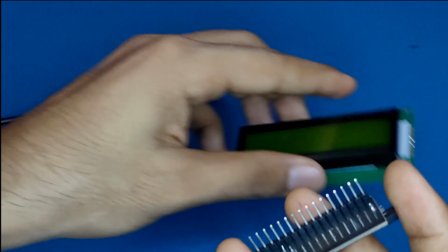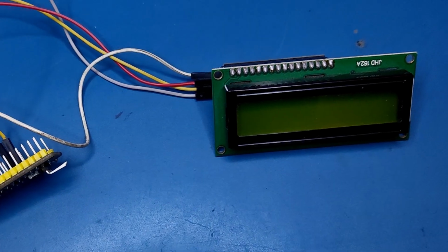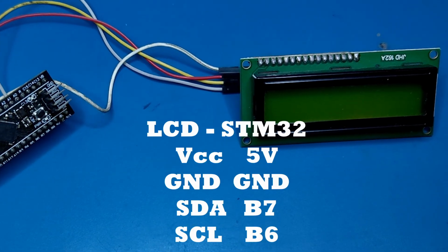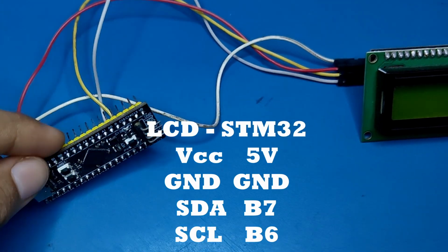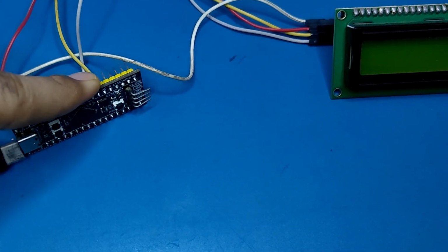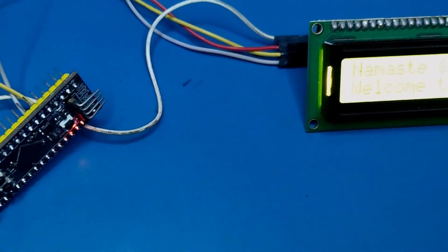Now let's connect the LCD to the STM32 board via our I2C expander. Alright, so I have connected the LCD to our STM32 board via the I2C expander. VCC to 5 volt, ground pin to ground pin, SDA to B7 pin and SCL to B6 pin. All set. Time to connect the USB-C power cable.